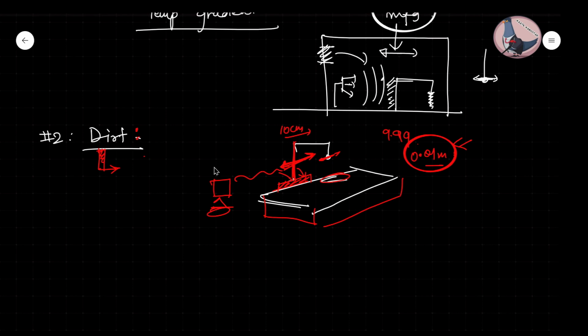Fine, because every time it will not be so convenient to pick the job and go to some far place where it is completely isolated from vibration or dirt, specifically a CMM facility or dimensional inspection facility where you will be doing the checks, and then bringing it back to machining for corrections. It is not always possible. So what they do, just to save time and transport, this is the machine shop. Just close to the machine shop or inside the machine shop only, they will be putting the CMM. So measurements can be done very quickly. If there are some corrections, it can again be sent to the machine shop. Again, some corrective actions are done, and it is sent back for measurement. So just for that sake, it is kept very near.